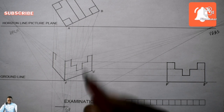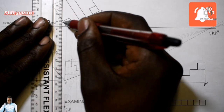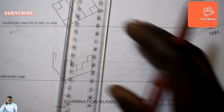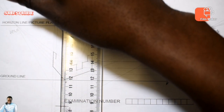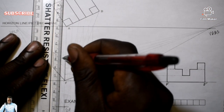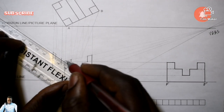Okay, so now we are going to move from there till there. So take this point to stationary point, this 2-point perspective, take it using your 30mm ruler. There you go. Once it touches picture plane, go vertically down, faint. So there you go. So now, which means from here till there, I must draw it dark. Dark. There you go. You understand? So now I close it here.